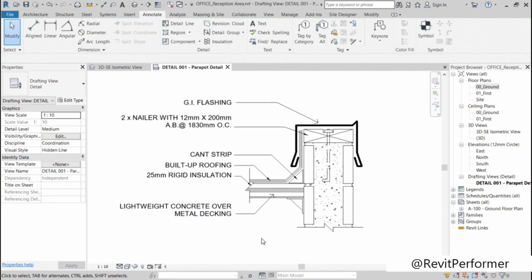The idea is you want to convert all of that slowly but surely to Revit text and Revit leader lines coming off of the text. It's very quick and easy to do, and you can see how quick it is just by deleting what you don't want and then converting the text to Revit text with a leader line.